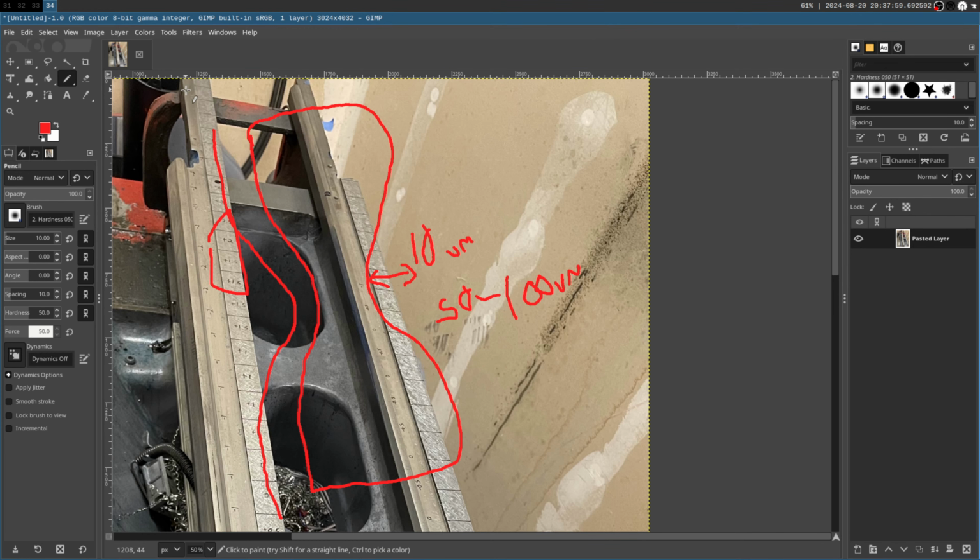And thus, these spots under the headstock that do not come in contact with the headstock itself, I can safely know will have no wear at all. So I can use those as a relative measuring point to determine the wear of the rest of the things. Because I know that at one point, everything was square and parallel to the plane through this small patch that hasn't had any wear, and because it's hidden by the headstock, it's not even like it could get bumped or scratched.